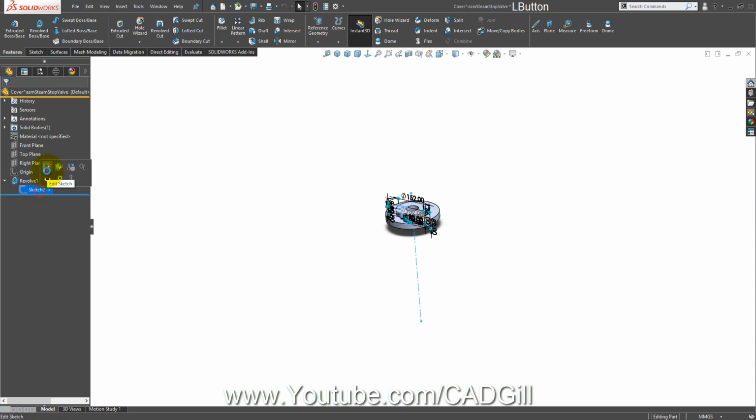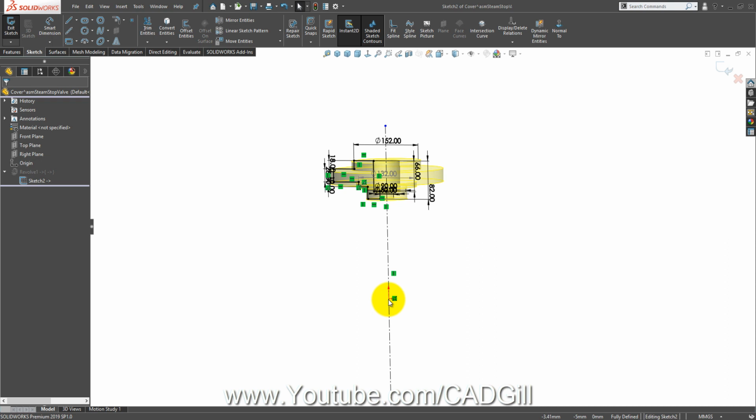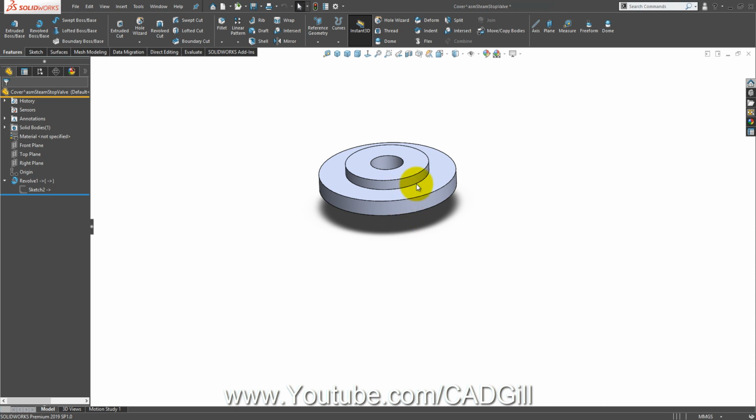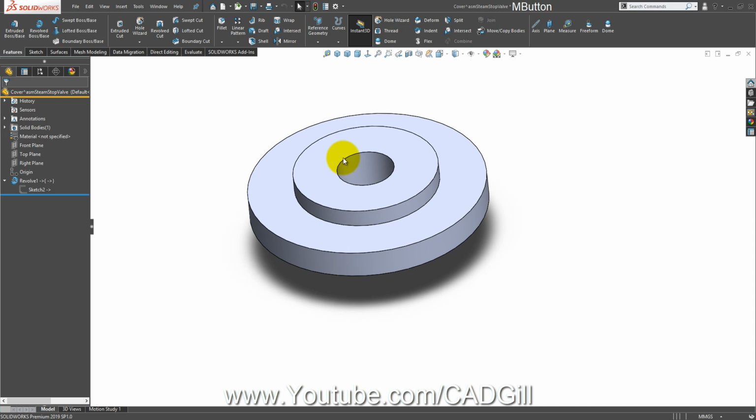If I show you the revolve sketch, this is shifted from origin because we are using the assembly origin. So this will be shifted, but it doesn't matter. The origin doesn't matter. Any reference you can use any point as a reference. Origin is not any bookmark or something. Yes, in case of a CAM software, you will need to move your part, but that is no trouble here.